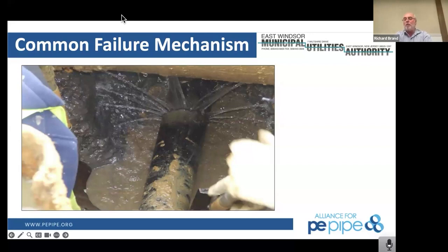And they've all been very well educated on it. They're fully on board. The issues that I had are mostly with the developers and the general contractors. The general contractors are the ones pushing back with the developers, who are then asking us to allow the use of ductile iron. And we explained to them the reasons why we don't, and why the MUA continues to install just high density polyethylene. So I still get my pushbacks every once in a while.